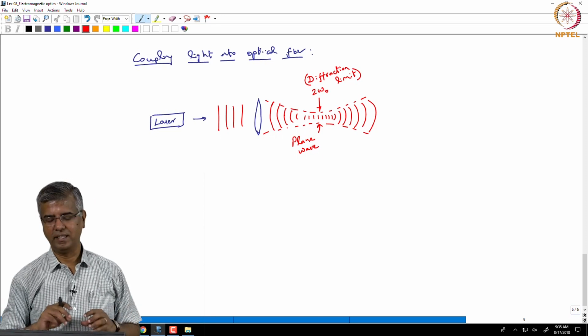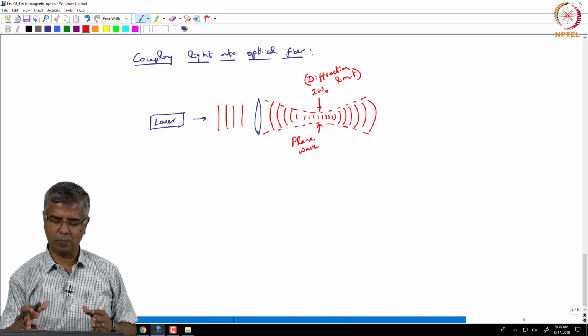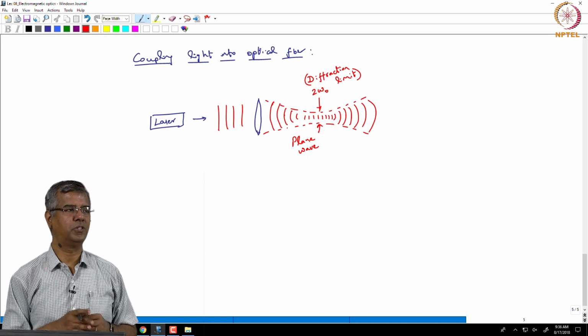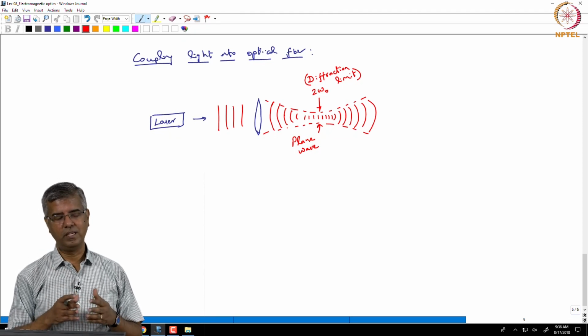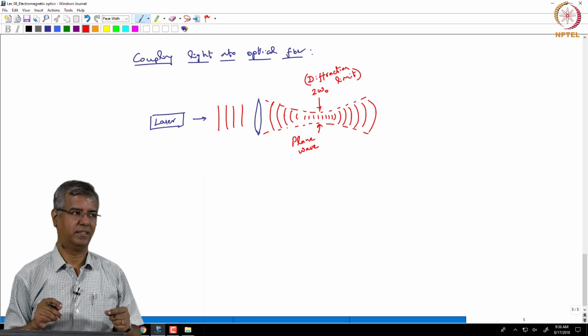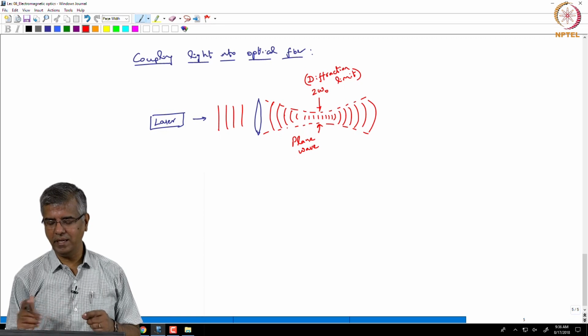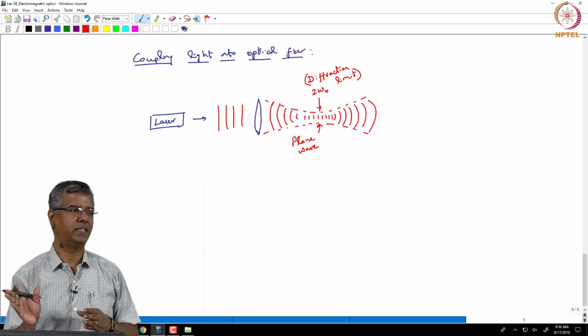You capture it, you put that optical fiber right at the focal point, in which case you can be sure that you have a plane wavefront, and that's an essential condition, because if you come in with any other curved wavefront, only the plane wave component that's oriented along the center will couple down the fiber.